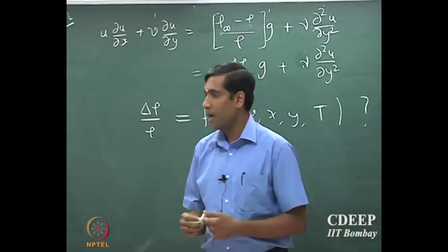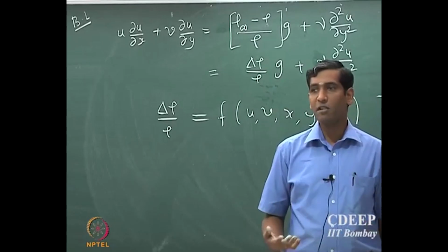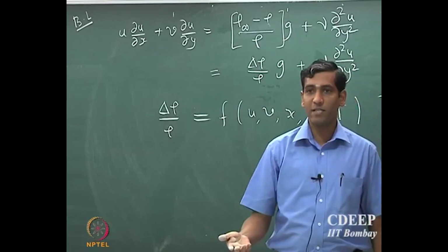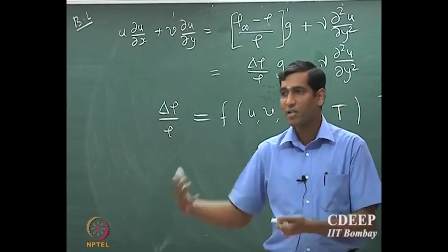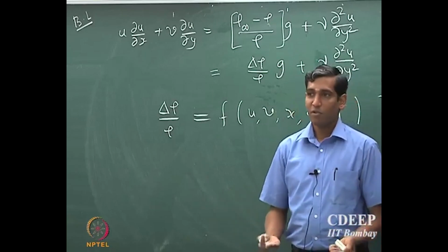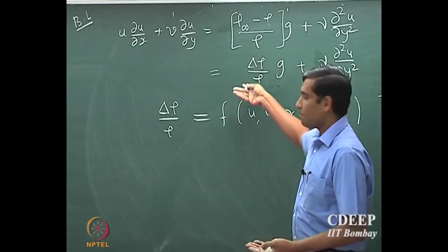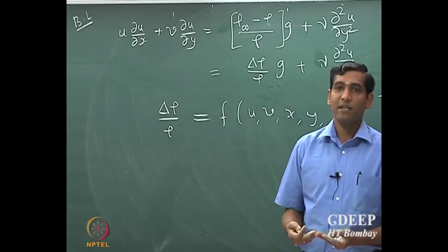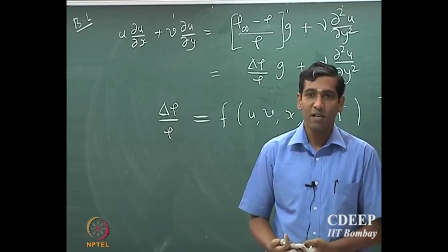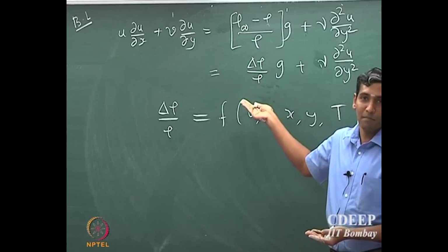Yeah, compressibility. So we said that the driving force, so note that in natural and free convection, the density gradient is a function of temperature, right? We said that the temperature difference is causing the density gradients and therefore they have to be related in some way. So far in all the cases that we looked at, the momentum boundary layer equation did not have any temperature dependence. It was independent of the temperature and concentration. So now we will start seeing dependence of temperature on the momentum boundary layer equation.